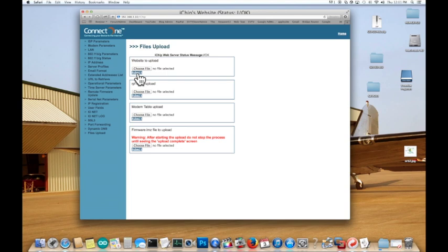We have downloaded the latest software, downloaded the libraries, installed Arduino, made our connection and checked our serial port, and compiled the new software to it. And then got on wirelessly and seen our web interface. And now we've gone behind the scenes and pulled up the Connect One maintenance screen and clicked on Files Upload and uploaded the latest image of our JEVCU software.